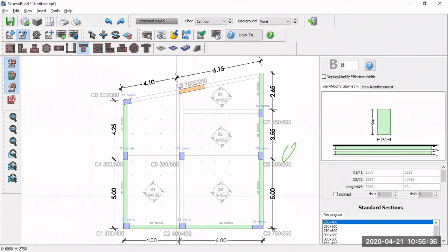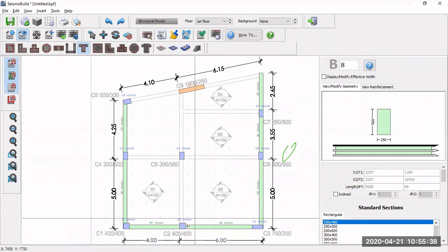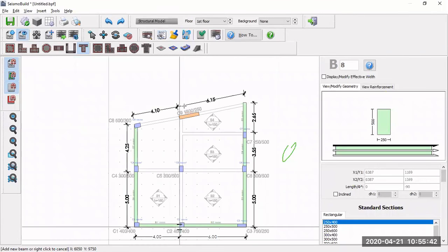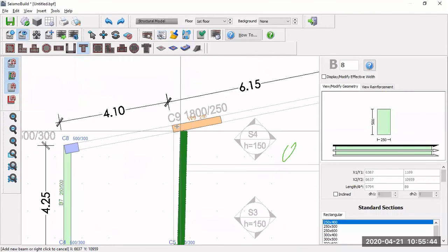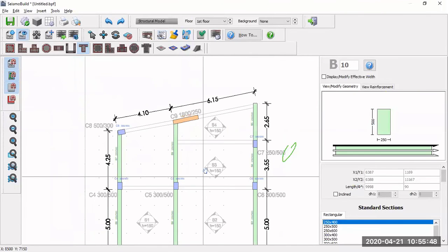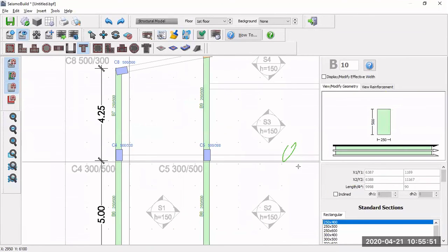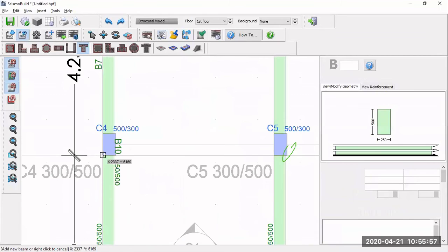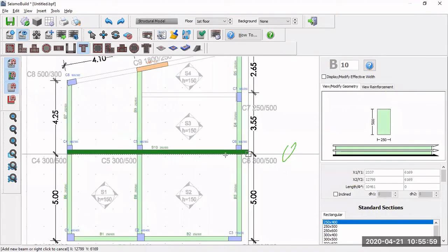Now we do the insertion for this beam, the same insertion point from this point to the top. Okay, so it inserts the two beams for you straight away. And then now we insert this beam here. Maybe we select the bottom insertion point, easier, and do here.